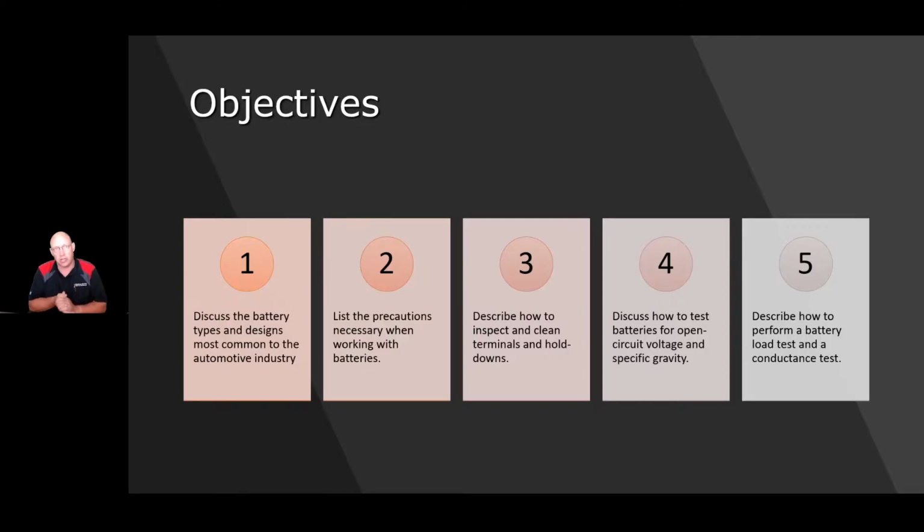Okay, discuss how to test the batteries for open circuit voltage and specific gravity. I'll show you a quick test down and dirty, and then when you come to lab, that's one of your labs you get to deal with and work with. Okay, and then we're going to describe how to perform a battery load test. Load testing today is kind of an old school method, if I might say it that way, with great caution, but there's still a valid purpose for a load test.